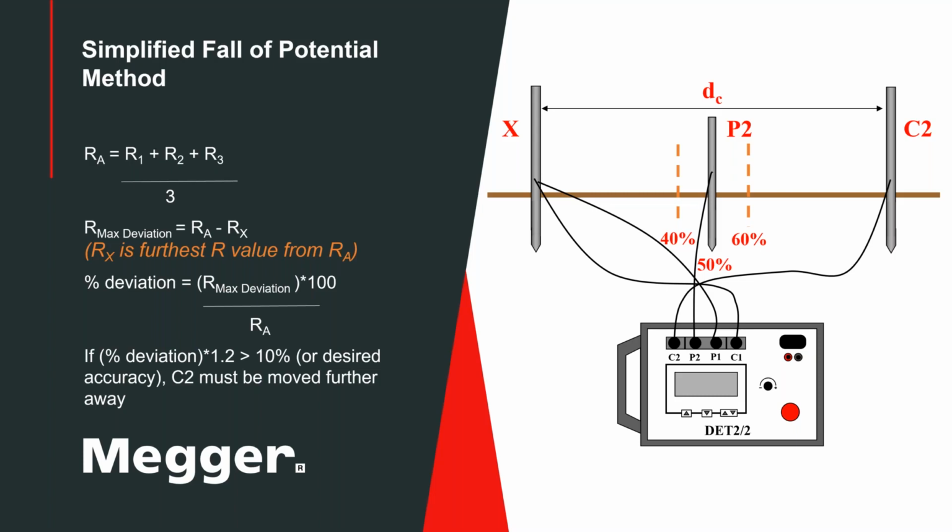But in most situations, they won't be exactly the same because of soil variance, especially at graded sites. You have different types of soil at different spots. And so usually the 3 measurements might vary a little bit. And so the operator can just say, oh, they're close enough. That's good. I'll accept this. And this is what a lot of veteran operators are actually doing. But if you have to submit your test result to a third party, it's a good idea to have something objective to submit. So then do the math and submit your result, and you're good to go.